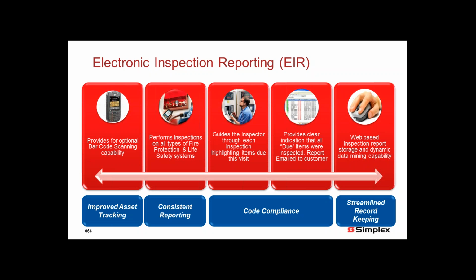And then we can use this information also to guide our people or the dealers that are out there working on the systems through their inspections. What devices were tested last time. We don't want to test the same devices if it's maybe split up into 50%. Sometimes we take a system and we'll want to visit the facility twice a year, but we don't need to check all of the devices twice a year. So we'll use this to maybe help guide the inspector on which devices need to be inspected at this time, and also give more information about maybe where they are. As Peter talked about, some devices sometimes are hidden and they're not always just obvious there for us to go get them. And we also want to account for all the devices. If you have 50 smoke detectors, we want to make sure we check 50 devices when we go out there.